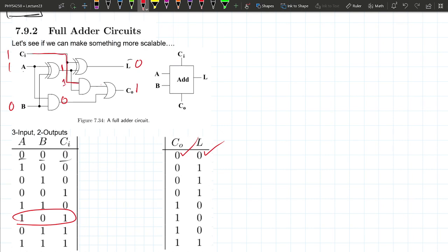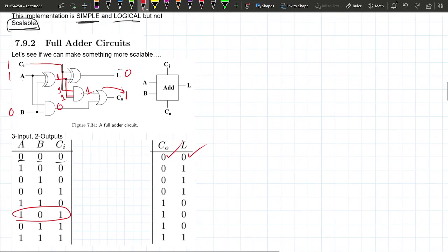And then this AND gate here comes from up here all the way down to here, which is all 1. And this one comes from down here. This is also 1. The AND between 1 and 1 is going to give you a 1, and therefore the regular OR gate between 1 and 1 should give you a 1 as the output. So at least we checked this one. Oops, I didn't even point to the right place, of course. And you guys can check the rest if you want.